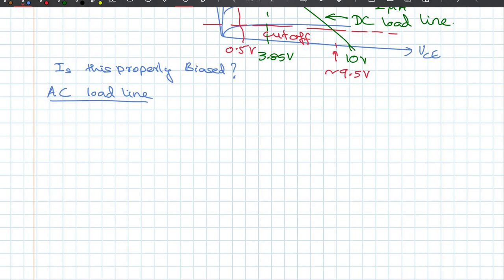Similarly, if you were to use inductors, these inductors have to have impedances that are way larger than your resistors. So if you are using an inductor, it should look like an open circuit, at least 10 times as big as the series resistor that you may have.